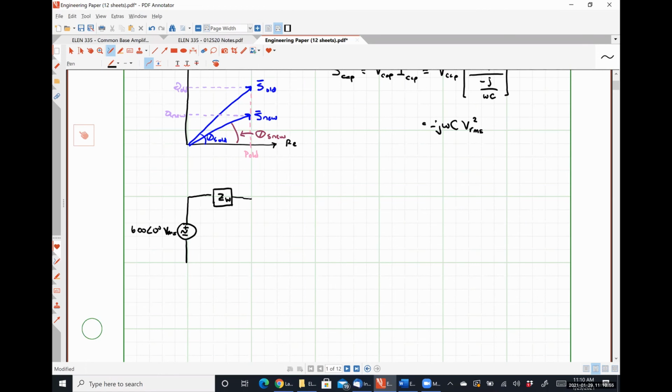And then connecting our source is an electric motor, which I'm representing with a circle with a letter M in it, that has a specific impedance of Z_M. And let's say it's got a low resistance, so something on the order of 10 plus j70 ohms. So low resistance, very high reactance, which would make sense for an induction motor.